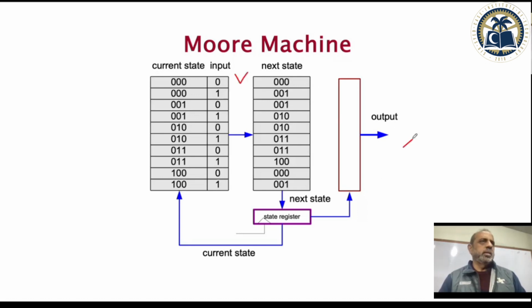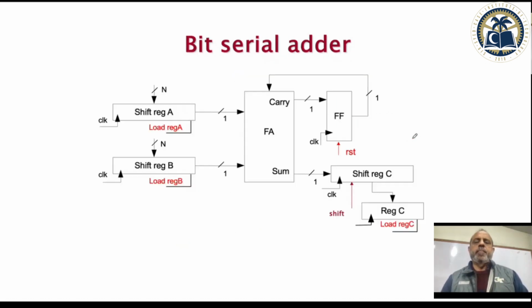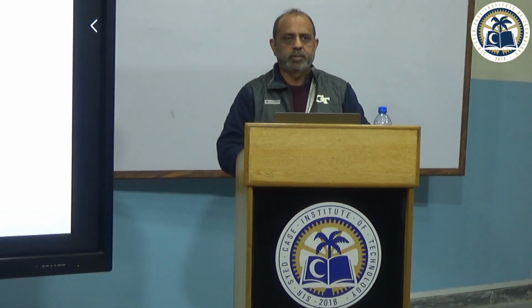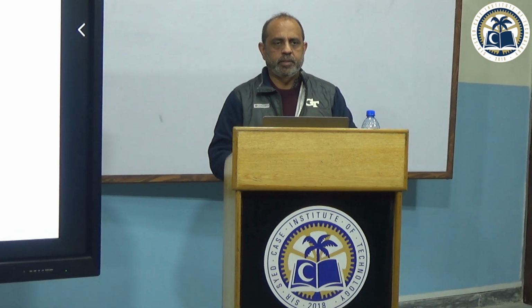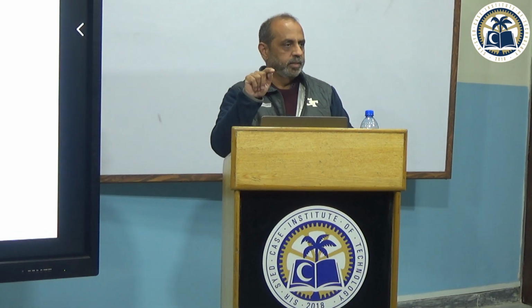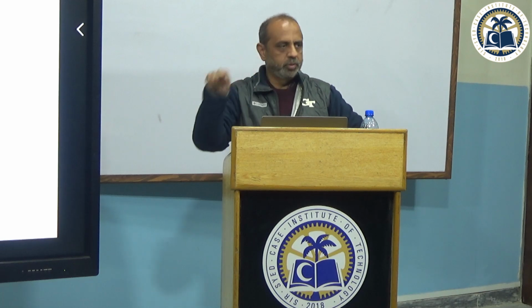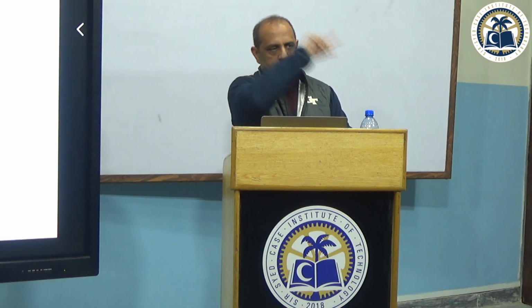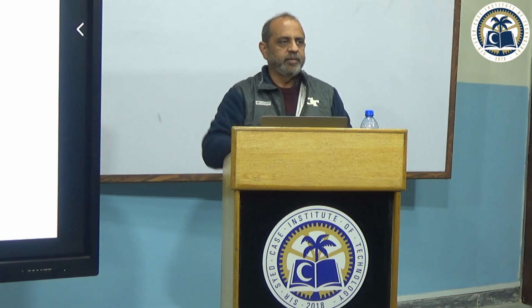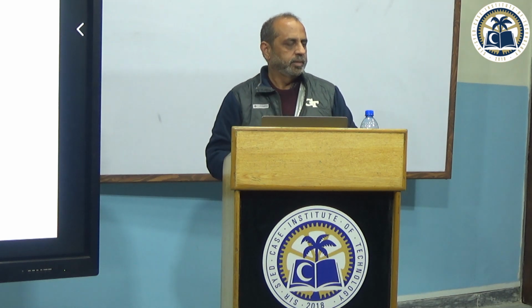But usually Mealy machines are used to have a programmable state machine. Actually, in many hardware designs, usually you just follow a sequence. First you do this, then you generate this, then you generate this, then you generate this. Like we were thinking about the sorting. It says first read one operand, then read another operand, then do the comparison, then go write back, then again write back both values, then read the next operand. So it's a very defined sequence of operations that you have to do.